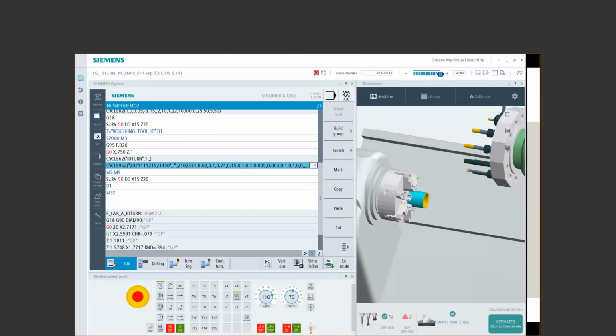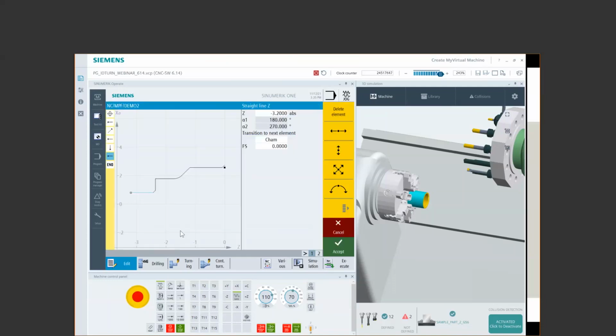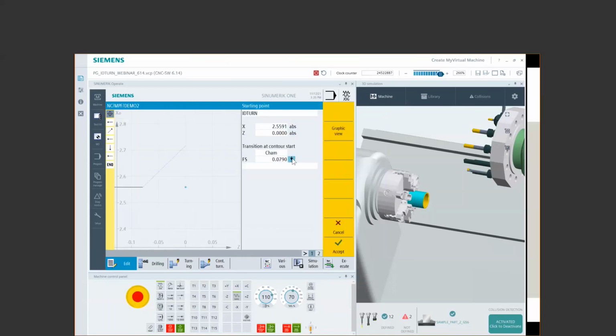Oh, I see what Dan was saying. He said when you're drawing the first chamfer, he was talking about that arrow scenario. So what Dan was mentioning is back here, when I first set this up, the arrow is cut direction. That is correct. So my tool would be moving towards center line when I am going to put this chamfer. So I think that's what he was referring to.